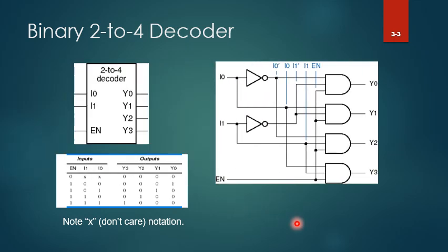So in digital electronic circuits, which is the basic course you've learned for digital design, you have learned how to transform the function table of the 2 to 4 decoder, using the knowledge or technique of truth table and K-map, to get the schematic of the 2 to 4 decoder. And this diagram shows how the circuit looks for the 2 to 4 decoder.